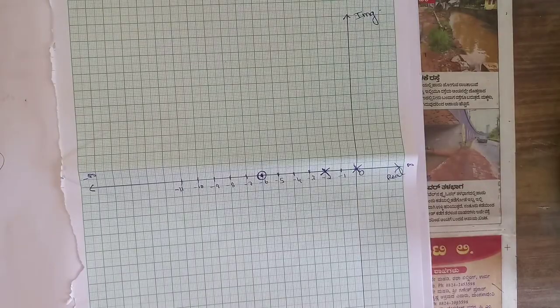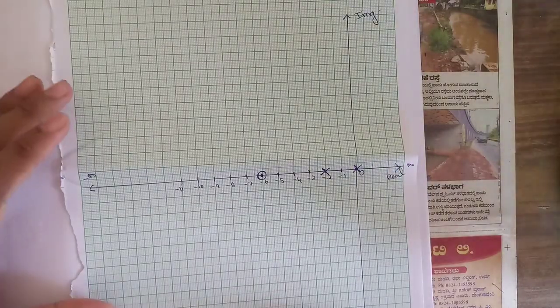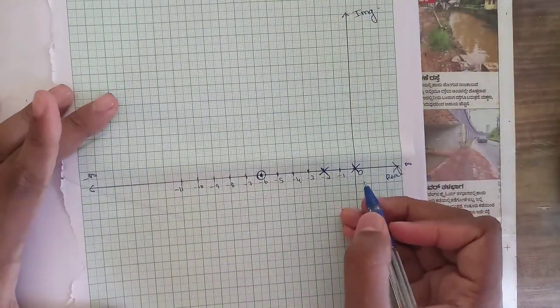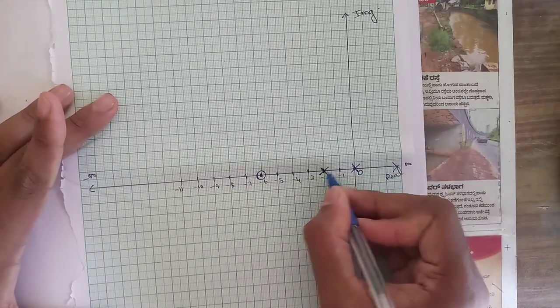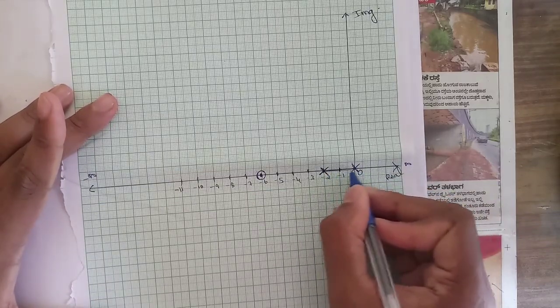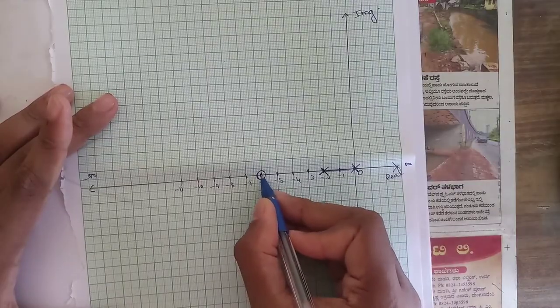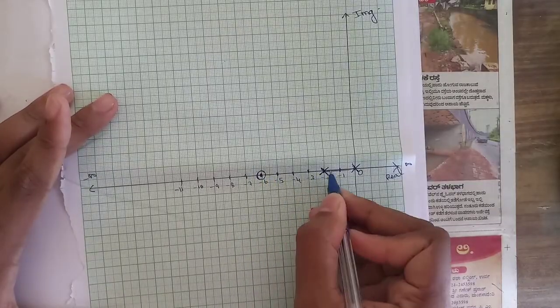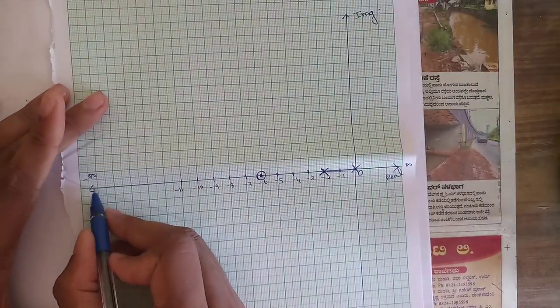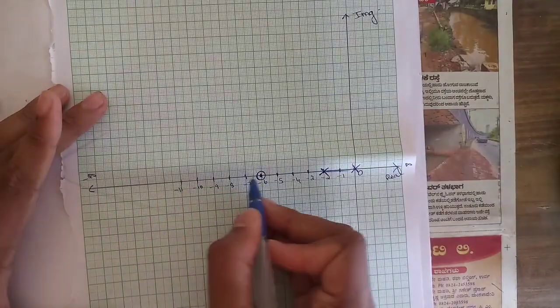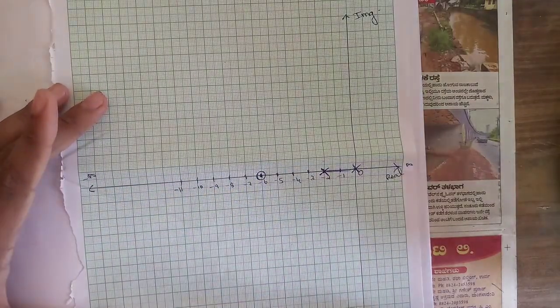Now we have got two breakaway points, because if you observe, from this pole we have this region, which is a part of the root locus, and from this zero to this pole, this region is not a part of the root locus, and from this zero to infinity, the whole region also is a part of the root locus.